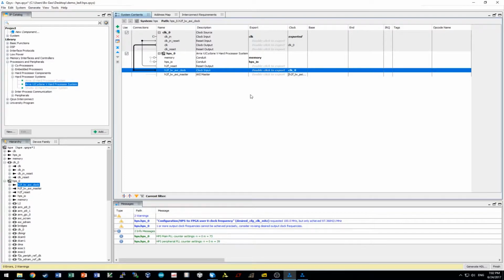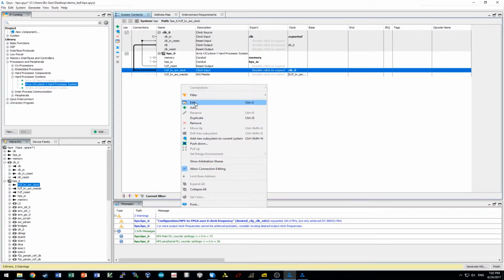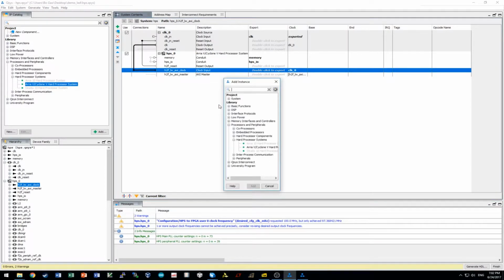And let's add some peripherals. So this time, last time we blinked one single LED, and this time let's say we have 8 LEDs. So how about let's run one LED at a time, from left to right, and then go back. So a looping LED pattern. So let's add a parallel I/O. Let's add something. Parallel I/O bus.